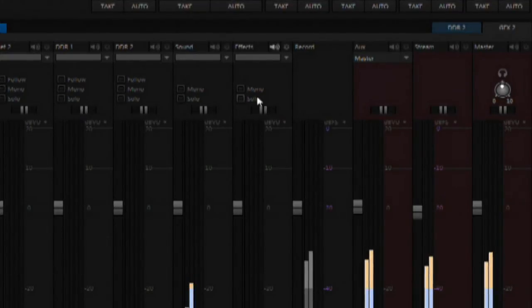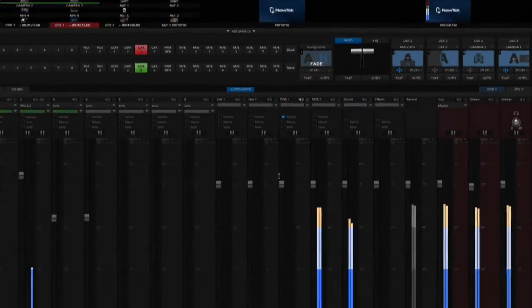The internal audio mixer also features audio follow video. This means that the audio can automatically follow the video production. This also works with color groups if they're active. When follow is turned on for an input or for an input within a color group, when that input is switched to, its audio will fade up with the transition. When that input is switched away from, its audio fades out with the transition.